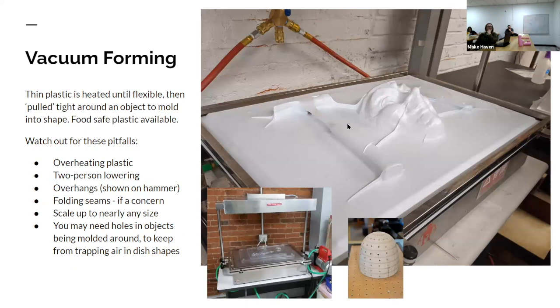There are some limits, pitfalls. There's strengths and weaknesses. Like doing the hammer is pretty hard. The face is actually pretty good as a thing because it's not a ton of stretch. But you've got to think about how you want to vacuum form. And the more you want to play around with that, the more we can help. If you have a big object like the face, I'm going to guess somebody probably drilled holes out through this guy's eyes so that the vacuum could be pulled through. I know it's kind of terrifying. So that the air could be sucked out from below. Otherwise you get this trapped set of air that wouldn't have anywhere to go.